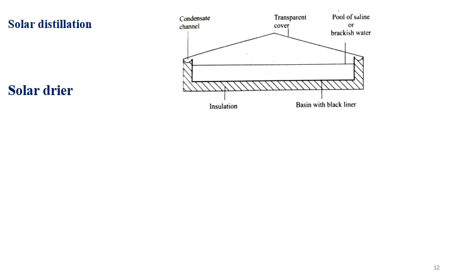Saline water can be replaced in the operation by either continuous operation or batch by batch, that is, batch production. Although there are numerous configurations of basin type units, their basic theory is identical. It uses the principle of rain; it will mimic that. The basin type solar still has produced distilled water at a cost per unit of product lower than other types of solar equipment, and is the only type in operation.